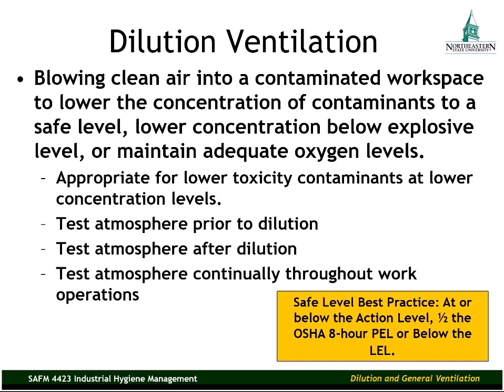And also, best practice, if you have a worker in a workspace where there are contaminants or there's the potential for contaminants, testing should continue throughout the work operations. Wearing a personal air monitor, for example, a personal air monitor that's calibrated for the types of contaminants that are likely to be in that workspace.